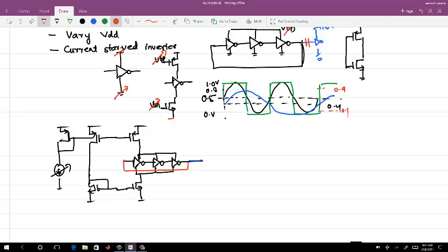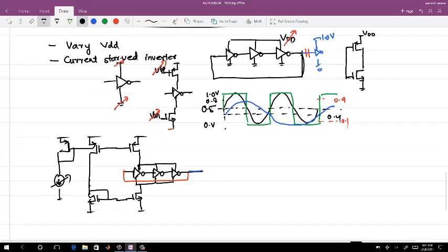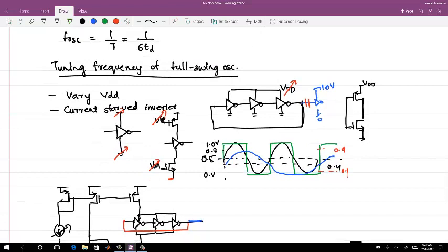No, the thing is different driving is, one thing is if you do not take the bulk into account for the PMOS, you should tie the PMOS bulk. But you can size them only at one particular voltage. The other thing is, the bulk of the PMOS for the inverter, you tie it to source. If you do not tie it to source, then you will see a threshold voltage variation.